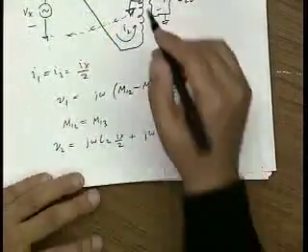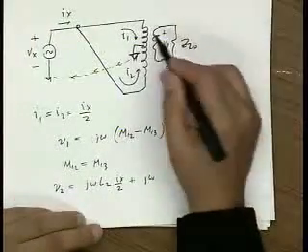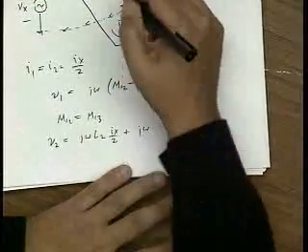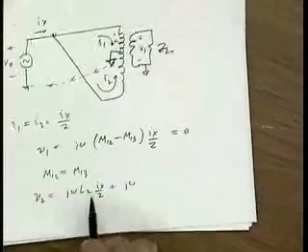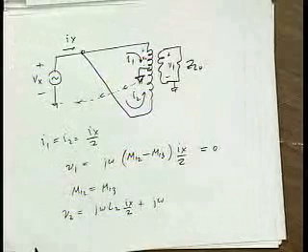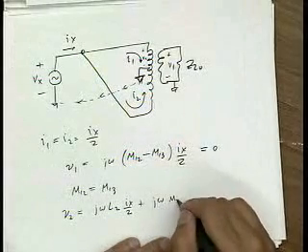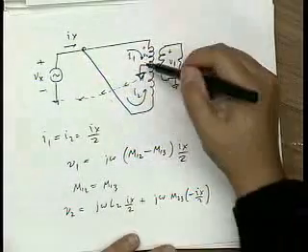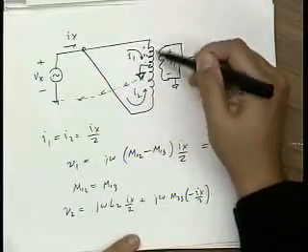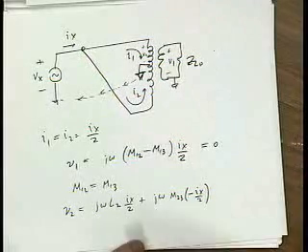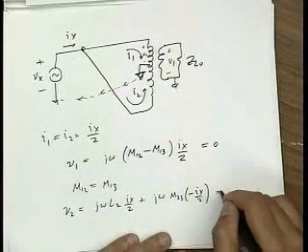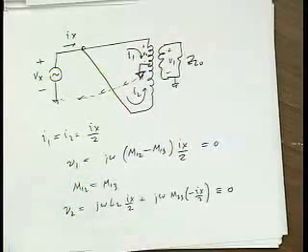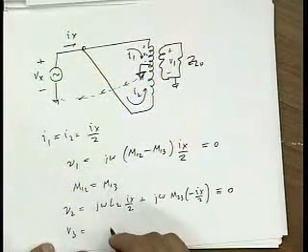On the other hand, I could pick up V2 from the LO port. I'm not in the clear yet. But the idea is that if I look at voltage V2, let's say this is V2, then it's j omega L Ix over 2 plus j omega M23 times minus Ix over 2. That's the coupling between this winding and this winding. And again, because the currents are out of phase, this goes to 0. And assuming these are tightly coupled, and similarly for V3.